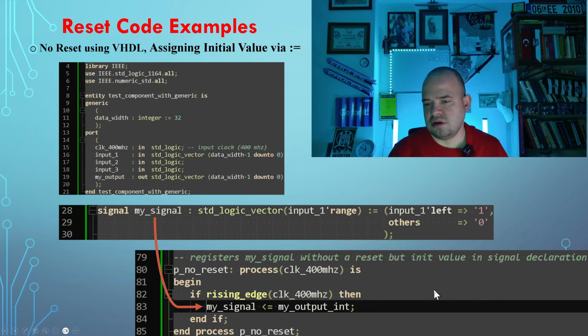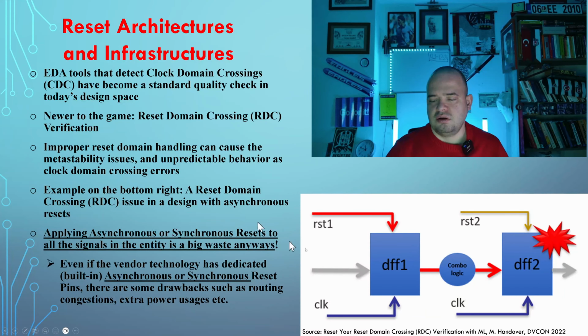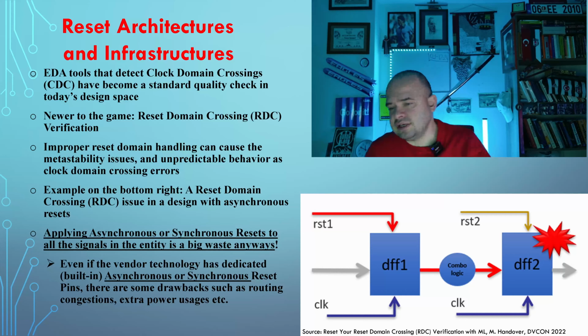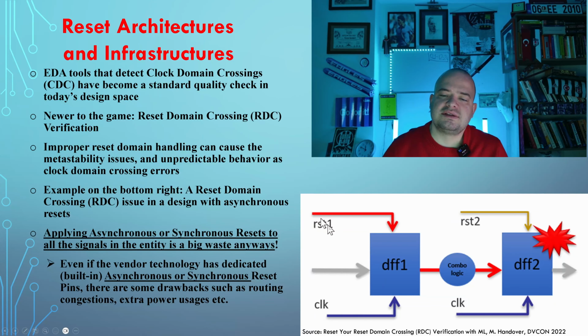In this scenario, if you are using that duplicated reset synchronizer circuitry, then you will reduce the fan outs, and most probably if your FPGA technology is good enough, you will get positive recovery slacks. But now you cannot guarantee these two reset signals are getting their reset values during the same clock cycle.